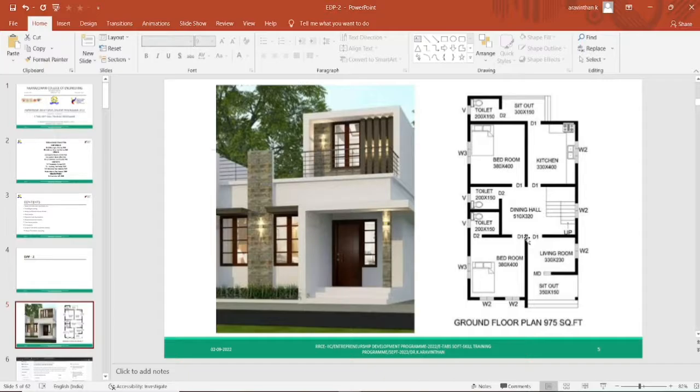For any commercial building, we will have 4, and in the case of any library or storage structure, it might be a cement storage or goods storage. If we have something like that, we will have 5 kilonewton per meter square. So as of now, since we are constructing a residential building, 3 kilonewton per meter square is the maximum.